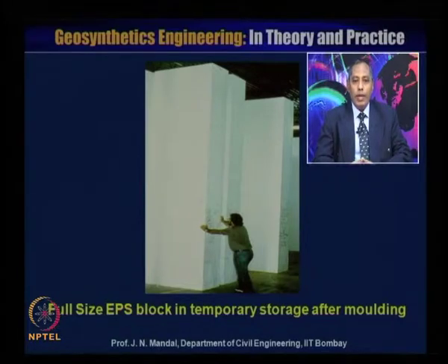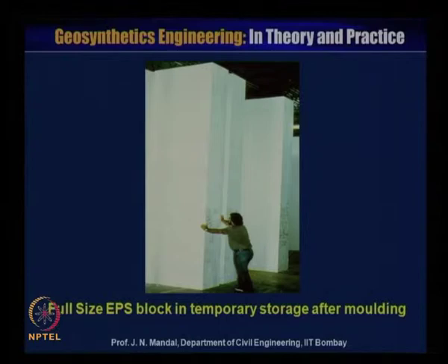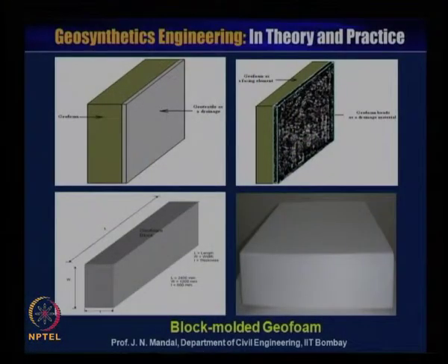So this is the full size of the block in temporary storage after the molding. You can cut the block as per your requirement at the project site. You can have various densities and various thicknesses. So these are the block molded geofoam or expanded polystyrene material.